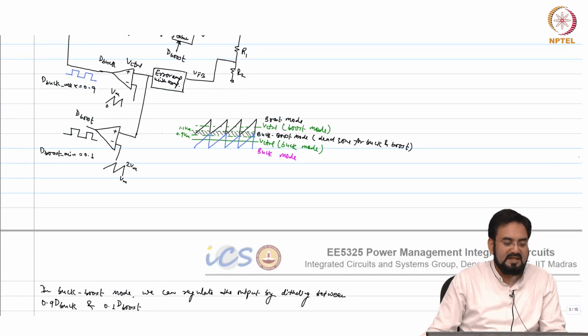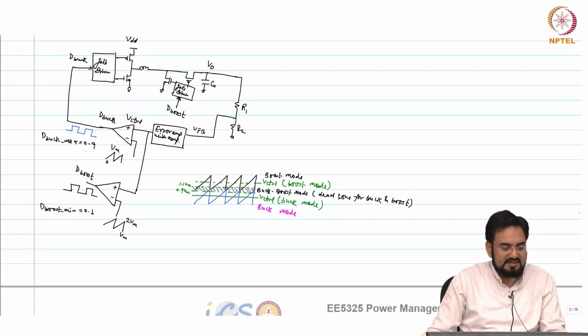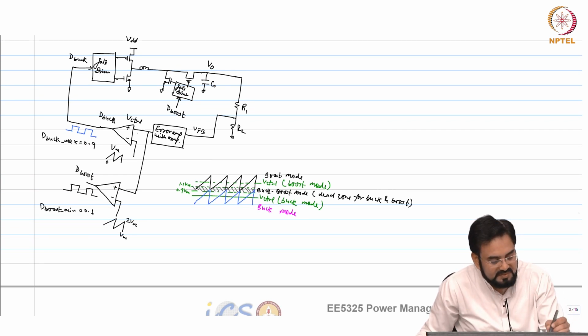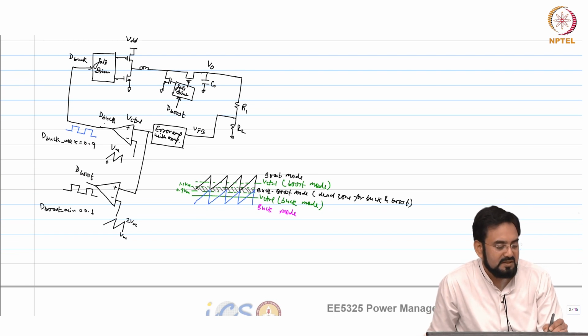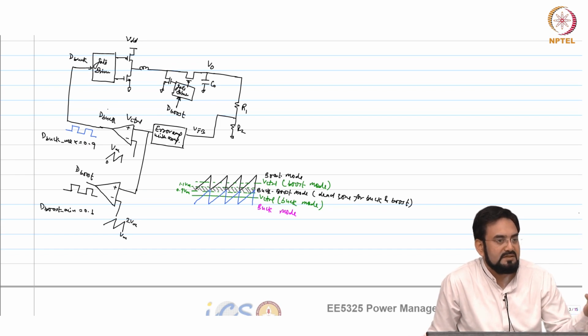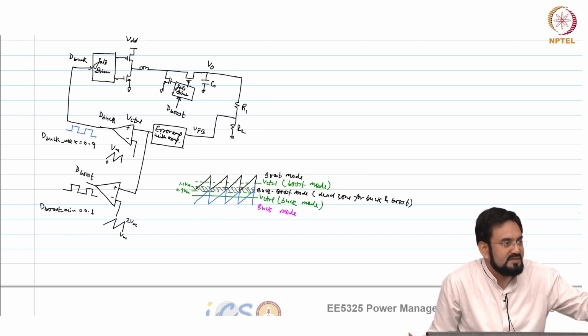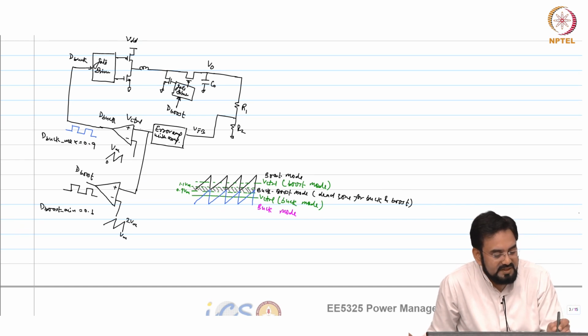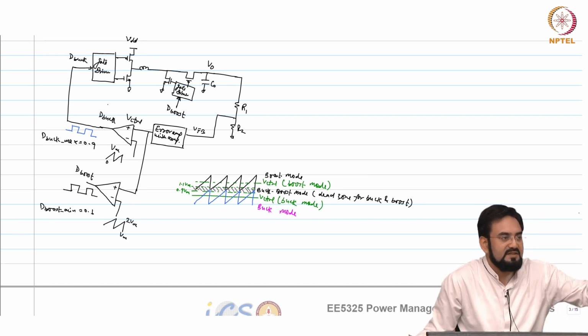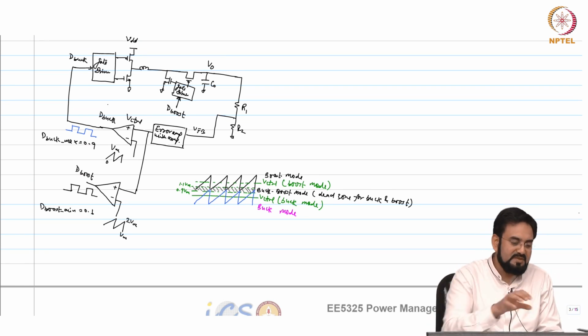So it is basically like subtracting some voltage from the V control. Let us say this is saturated at 0.9 Vm in buck, and when I enter buck boost mode, what do I want? I want the duty cycle to be 0.8 or so, but this V control is still 0.9. So what you do, you take the V control, and let us say 0 to 1 volt was your ramp, so 0.9 volt. From 0.9 subtract 100 millivolt, and that voltage will be given to this buck comparator, and that will change the duty cycle. So you have to do some math here in between.